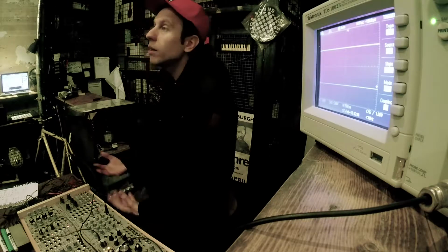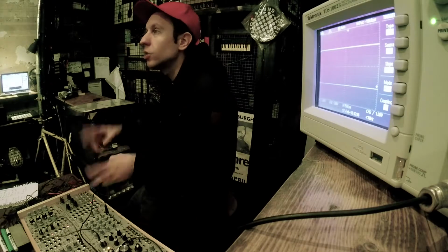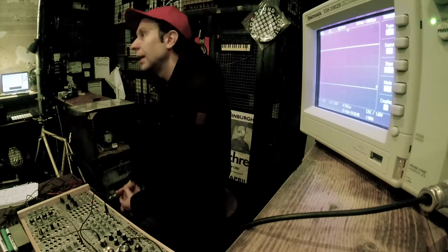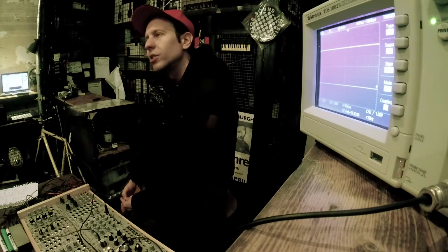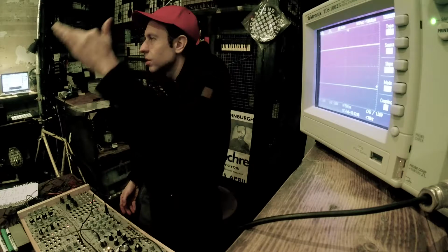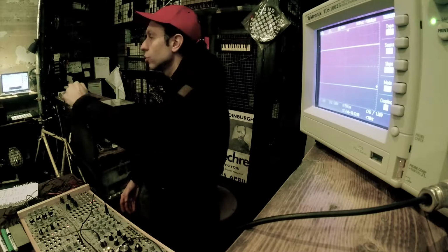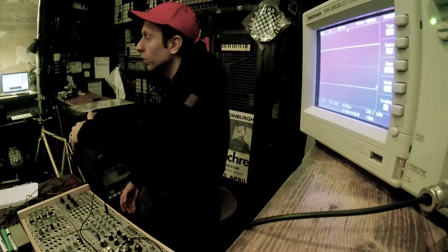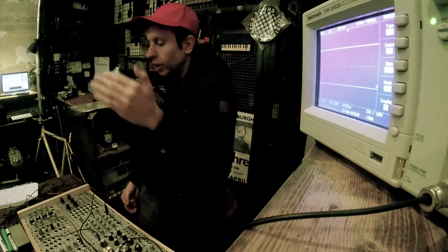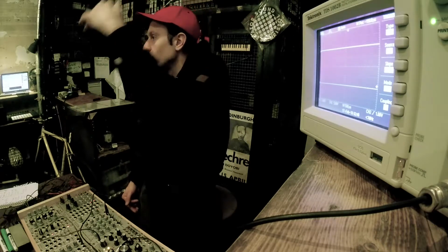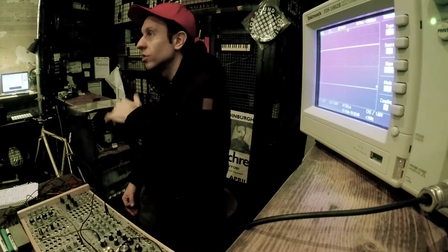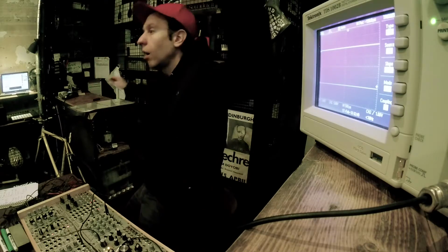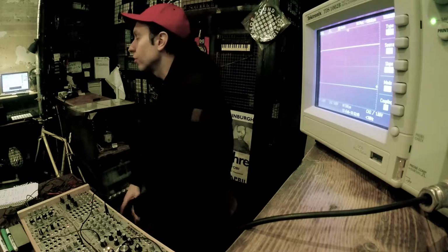You could say, well, it means that I can manipulate this color of noise with a filter. The thing is that if I want to have pink noise from white noise, I believe it's 3 dB per octave, might be 6, of continuous slope. And that's the problem with producing it, because with a filter, you would have a cutoff point, and then you get a reliable slope. But when you want to synthesize these noises accurately, then you really need a continuous slope over a very large range.